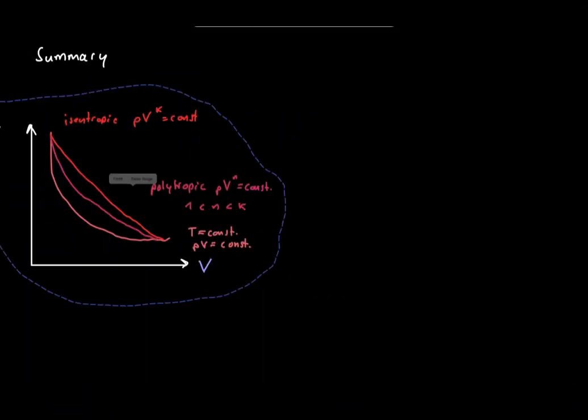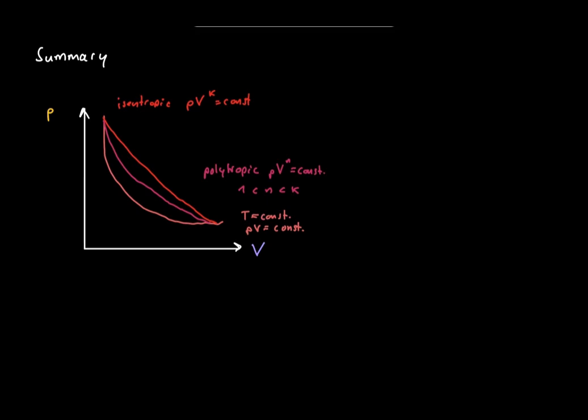To summarize, isothermal means constant temperature, adiabatic means no heat transfer. Isentropic means constant entropy and requires reversible adiabatic behavior. Polytropic is the more general case. It describes many real compression and expansion processes, and the exponent n tells us how strongly the temperature rises during the process.